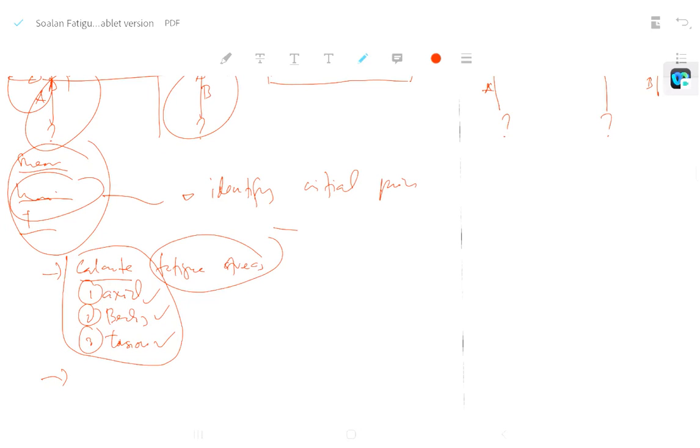Then you proceed to sigma EA and sigma EM. Right? Because there is no notch and no different diameter, you don't need to calculate KF. No KF. So the equivalent, combining the load, combining the stress here, combined.